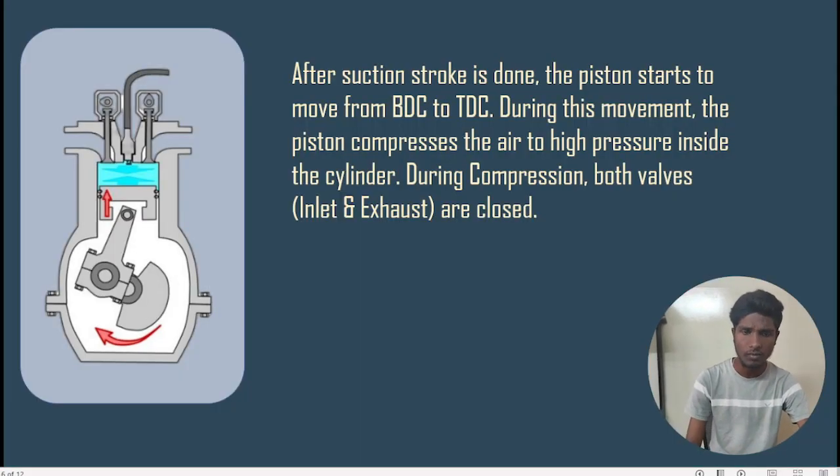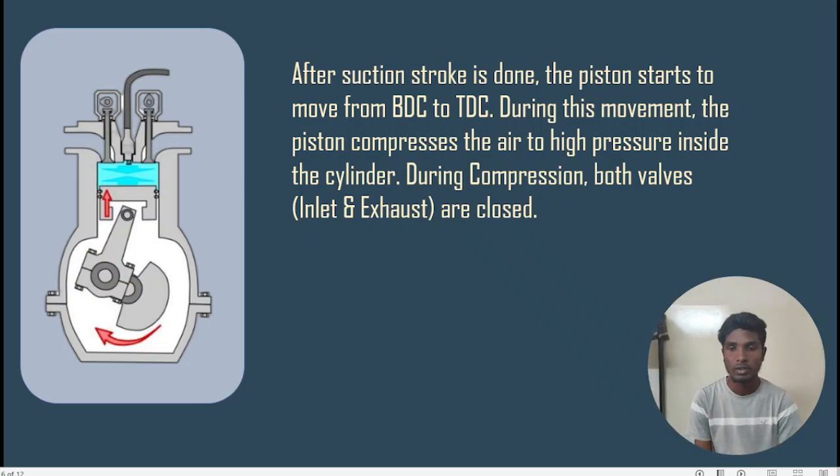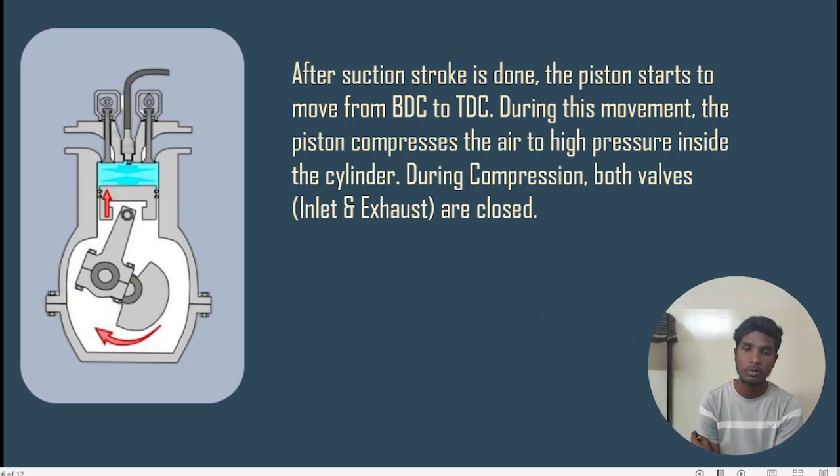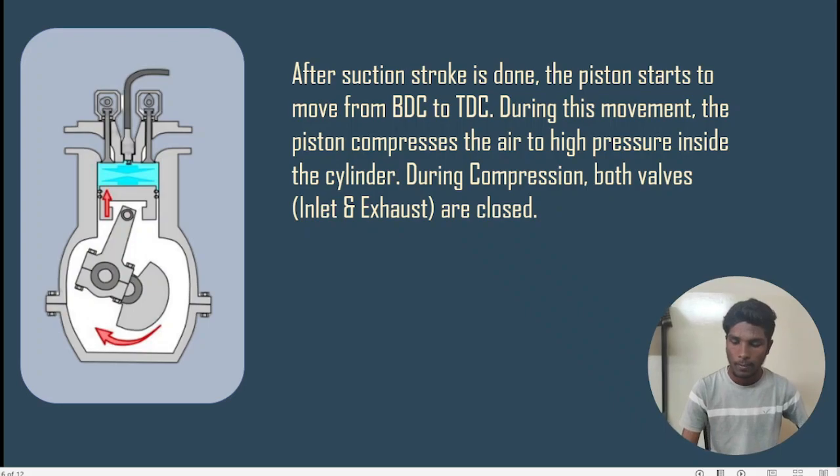Next, after the suction stroke is done, the piston moves from BDC to TDC. First it moved from TDC to BDC, top to bottom; now after suction it moves from bottom to top. During this movement the piston compresses the air to high pressure inside the cylinder. During compression both the inlet and exhaust valves are closed.